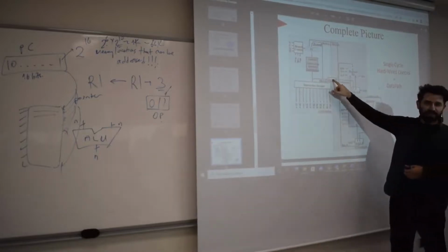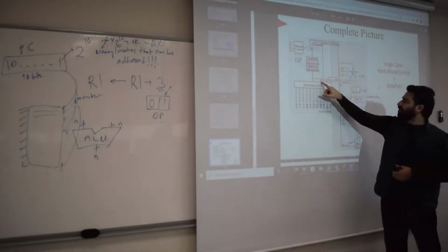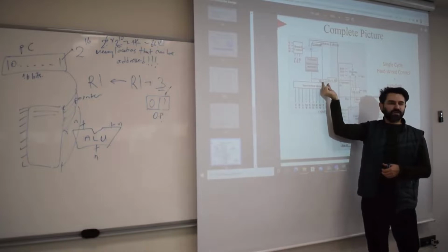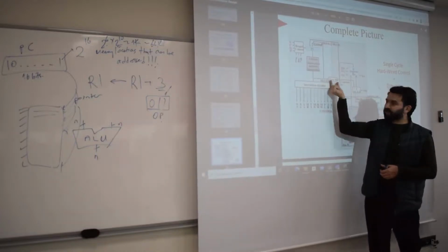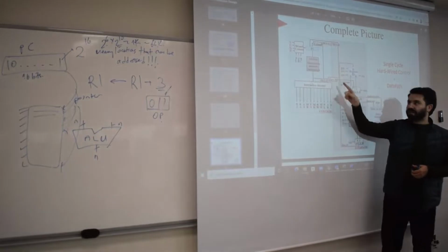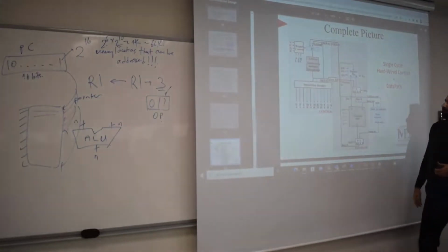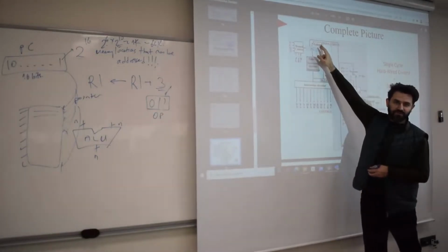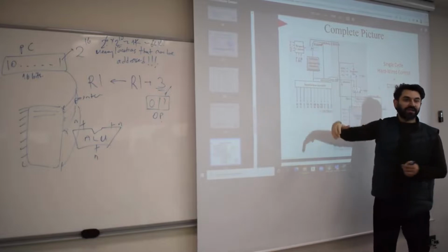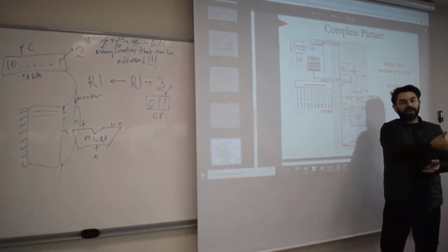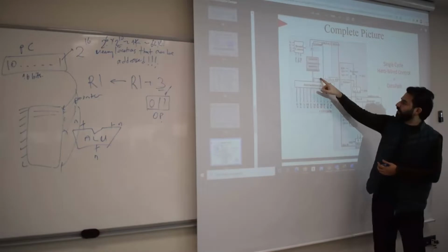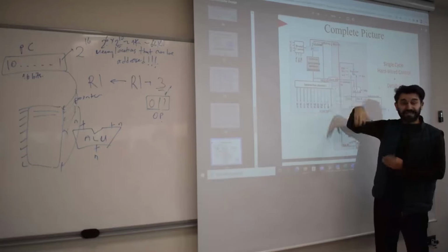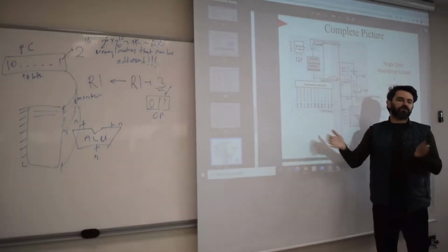You see, this 0 field wasn't here, but now it is, because if you've got an instruction coming in, we know that the least significant 3 bits were the op, right? But we have to put something here to make it 16 bits, that is the 0 field. So it's there. Here, sign extension is also part of the thing, because the program counter should accept some negative numbers in order to go back and go forward. However, this 3 bits here is just 0-filled. The reason being, we assumed in this architecture that the 3 bits are always a positive number.